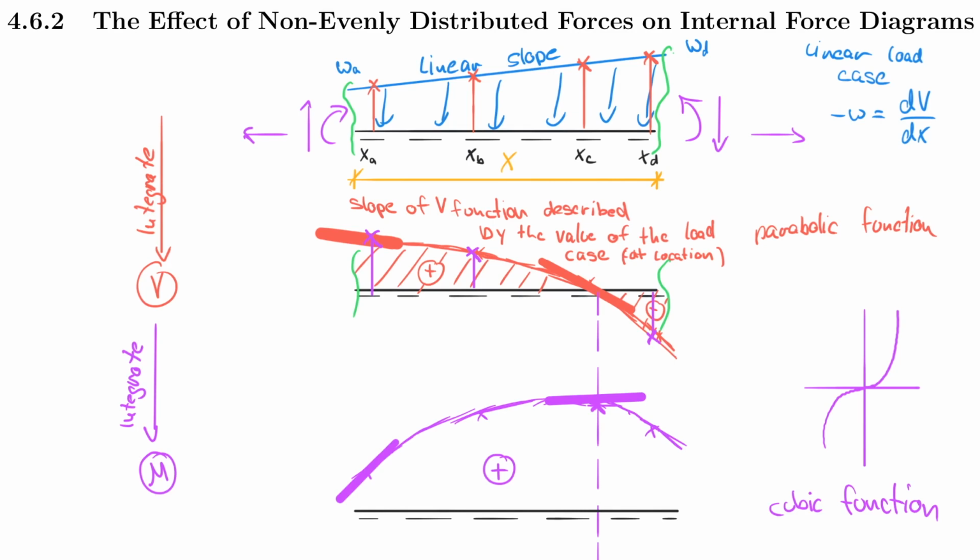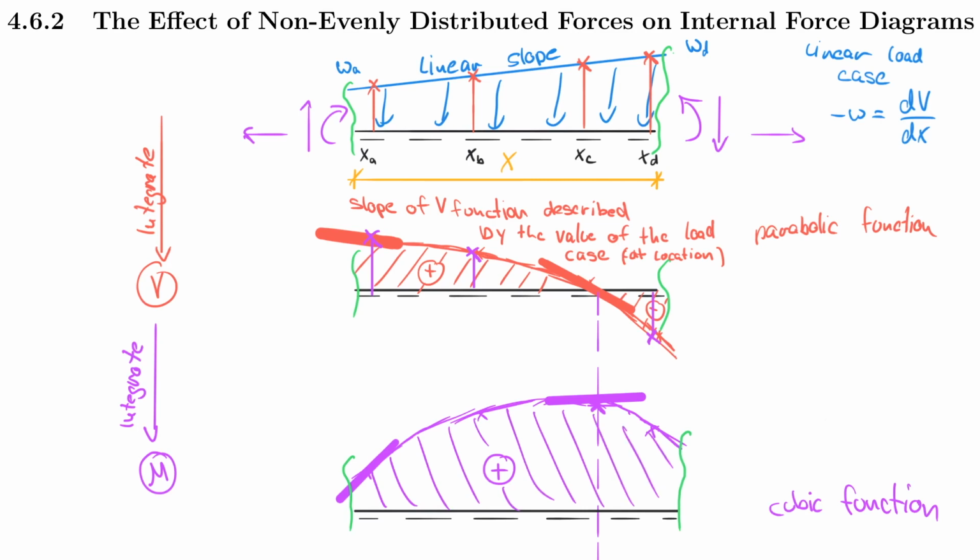So now I think we can agree that the graph here on the right is a very special case of a cubic function, and it does not always apply to our diagrams, because what we see here is a very specific case of a cubic function, and the way we actually get the slopes of that function is really through the shear force function. And therefore we now completed the cubic moment distribution for a non-evenly distributed load case. And this is a very simple load case. Before I talk more about that, let's just complete the diagram here, and let's agree that all of that is now in positive bending because the entire beam is smiling, as we discussed before.